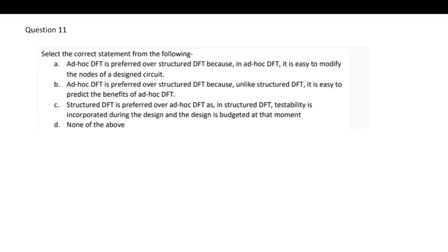So, which of the statements is correct? We have said that this ad hoc based method will affect the critical path. The structural DFT which we use, like converting the normal flip flop to scan flip flop, we do during the design phase itself. So at that time we take into account all the delay incurred by that multiplexer addition.